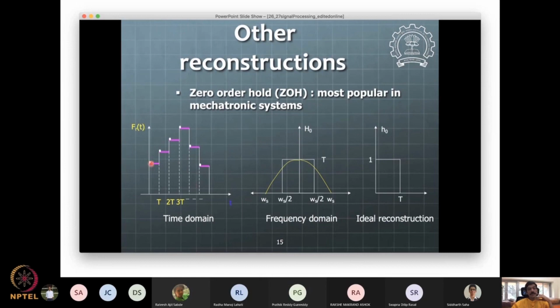And not just sampled, they are sampled and made a zero order hold like that. Okay, so this is important, not just sampled, but sampled and reconstructed as a zero order hold. That is a very important statement. Otherwise, if it is just a sampled signal, it will have just some mirror images. Okay, so there is a subtle difference between the two.